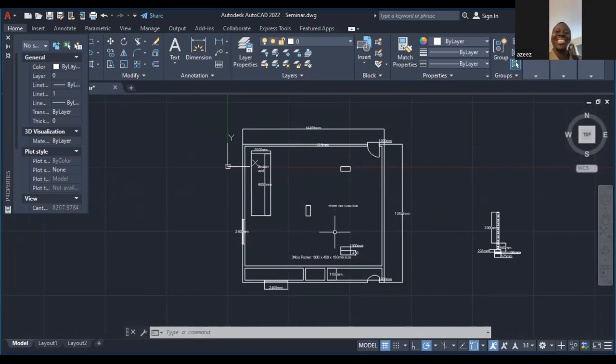Just say extension. There can be an extension of 600 here, 600 here, 600 here, like 2 feet. You know, a foot is 0.3, so like 2 feet extra on both sides. So the length has 600 at one corner and 600 at the other corner. That will make it 1.2 added to the length. Then to your breadth 600, that will make it 1.2 added to your breadth also. Then you are going to get your quantity in square meters.